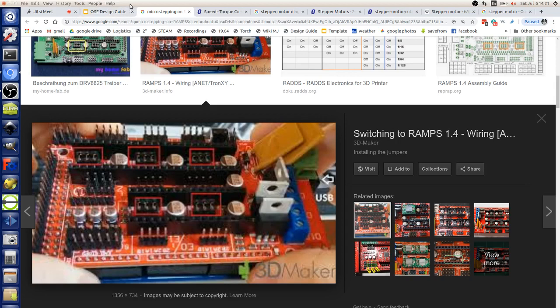The speed function, at that level, the stepper drivers interpret. They give you the pulse sequence, but the actual speed, all you're giving to the stepper driver itself is just step, enable, direction. Actually, I'm not sure about that. Who is doing the timing for the particular speed? Is it the Arduino that's saying, now turn it on and off? Isn't the speed in the G-code? It's in the G-code. The G-code is interpreted by Marlin, by RAMPS.